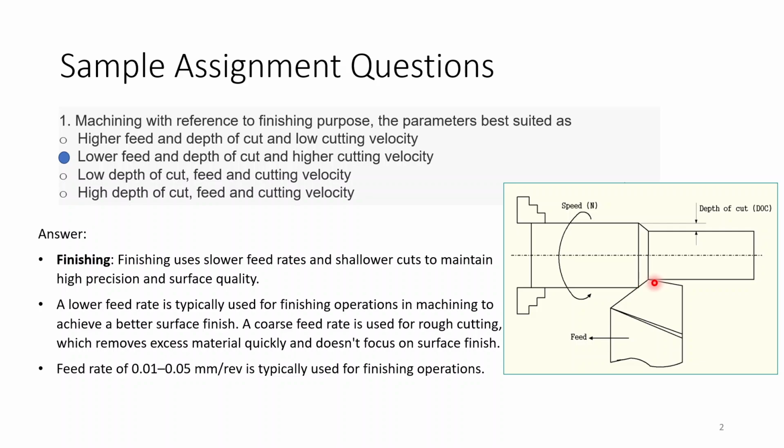What is the travel distance of this tool per revolution along this axis? That will be your feed, and cutting velocity will be revolutions per unit time.